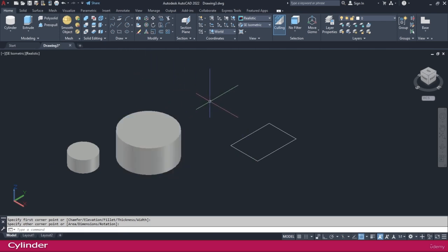If you need to make it horizontal, parallel to this X direction, you need to change this UCS. I will teach you later about this UCS very clearly, but simply I tell you, if you see this view cube, here it is right. If you need to make any geometry or any cylinder, any primitives, you can set these coordinates to right. Now you can see your X direction and Y direction changed.